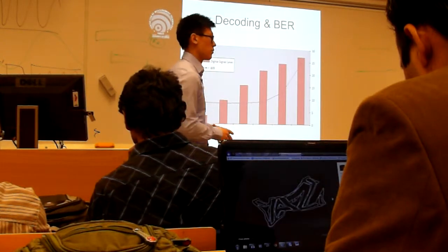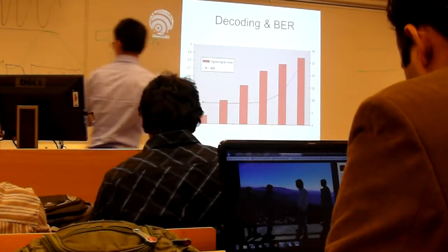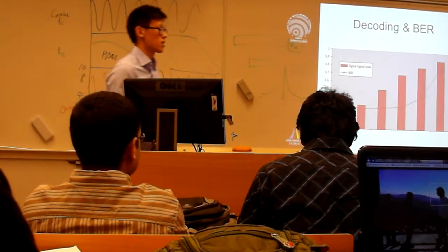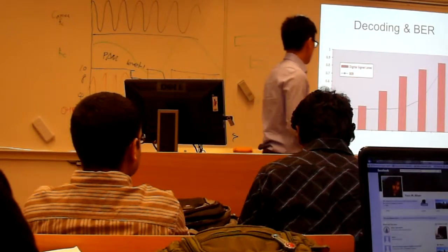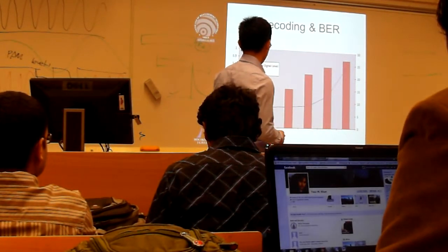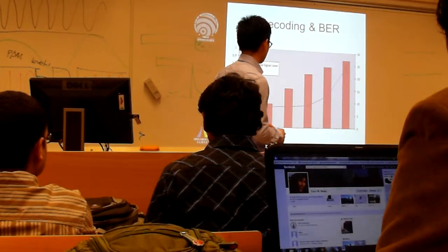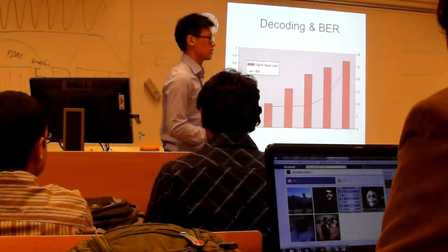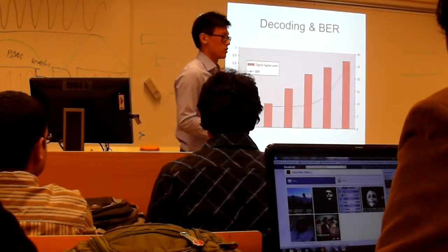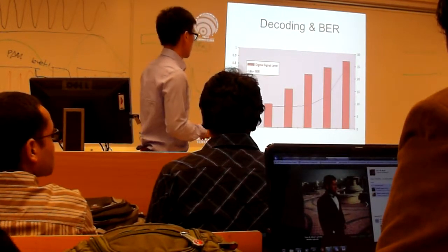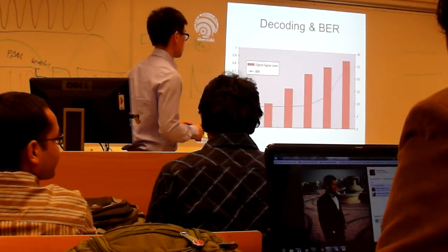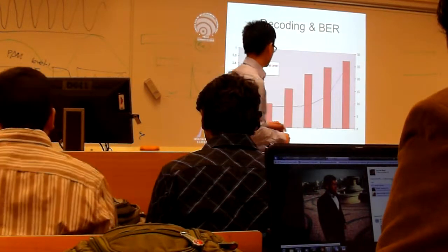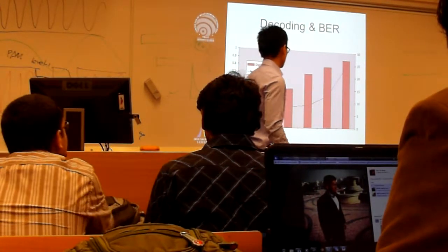This is easy to understand because a low ratio gives a big gap between those two levels, and it's easy to distinguish and decode. However, the small ratio will also give a big distortion in the analog information. So we need to find a proper boundary. As learned from the signal processing course, we know that the midpoint here is a good choice.